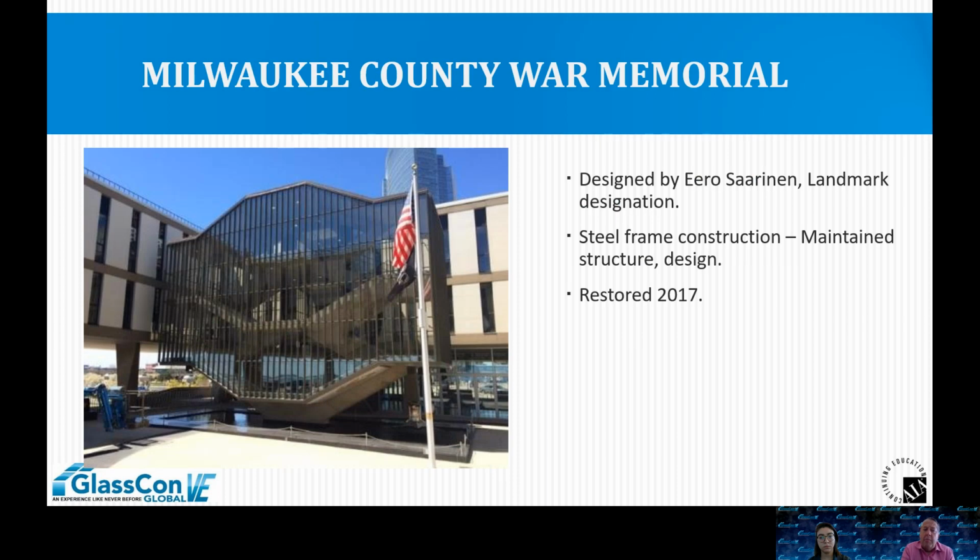The Milwaukee County War Memorial was another large project, done back in 2017. It was an Eero Saarinen designed building put in in the 1950s, 1955, I think. The architect was actually hired to do a curtain wall replacement because this is horrifically energy inefficient. It was non-thermally broken steel sash, stick built in place, and glazed with 1/4-inch wire glass.